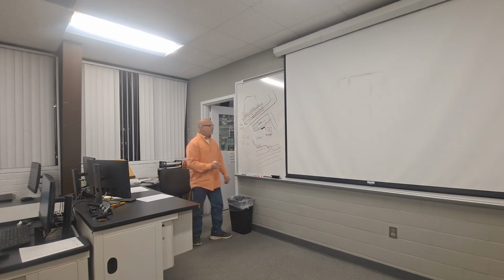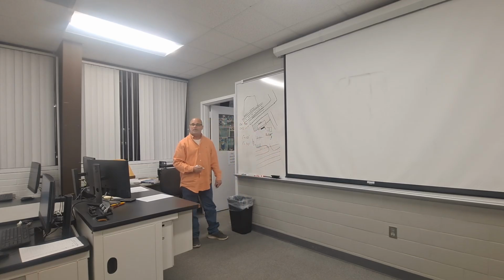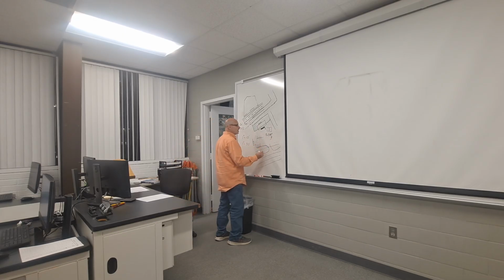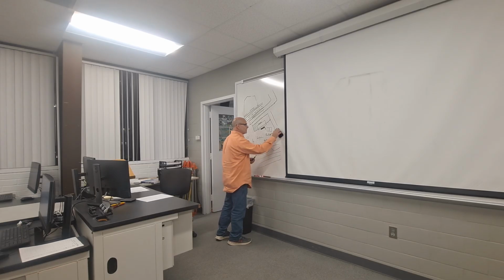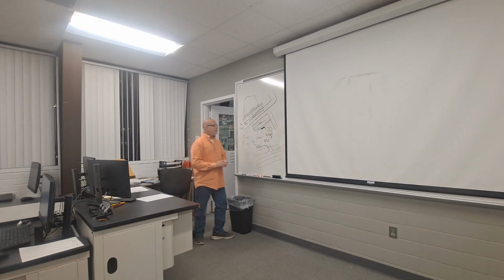When you go to type it in, remember, there is no degree key on your keyboard. We're not doing dimensions. You're not going to click on your angular dimension and have AutoCAD pop that angle on there for you. It's going to be typing those numbers in. So when you type it in for your project, you're going to do percent D, which will get that degree symbol to pop up when you're typing it in.